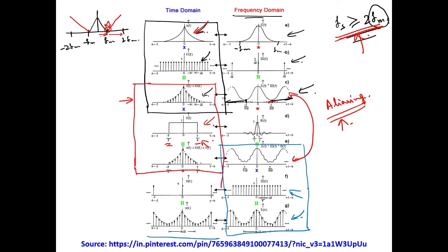However, if you look over here, your time limited signal is also getting repeated itself. After this period, from minus T by 2 to T by 2, the signal is repeating itself. And that is why, if you do not time limit the signal over here, what will happen? These signal components will be getting mixed up with the original signal components, and you will have trouble in analyzing. This is a bit complicated, but try to understand the mechanics, what is going on.